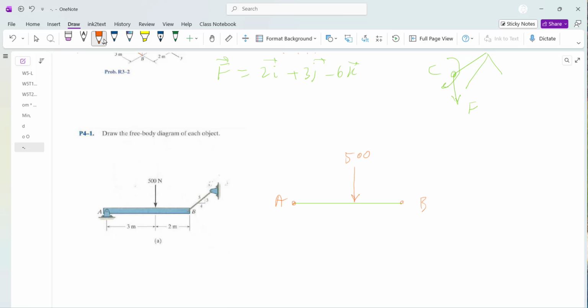So therefore, to free that, I have to expose the internal forces which were preventing this from movement. And since I don't know the direction of these forces, I assume they are parallel to my X and Y axes, in the positive direction.